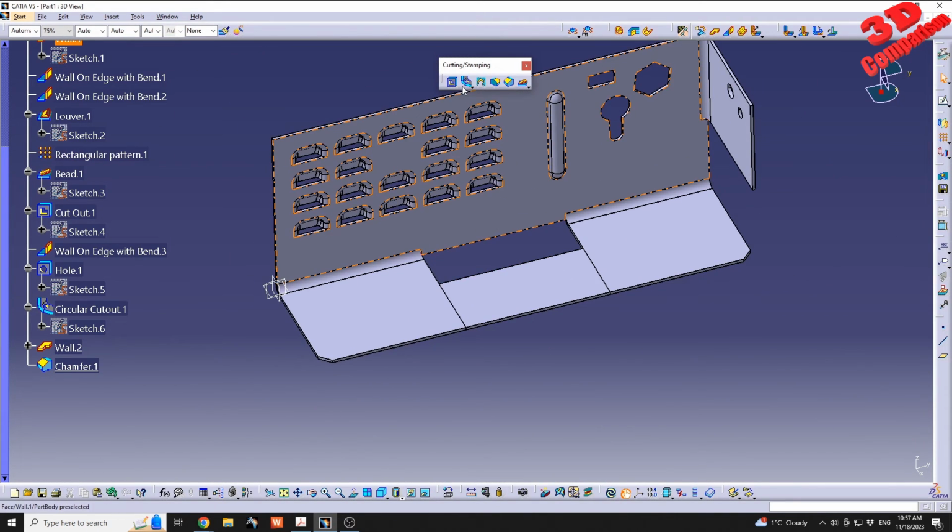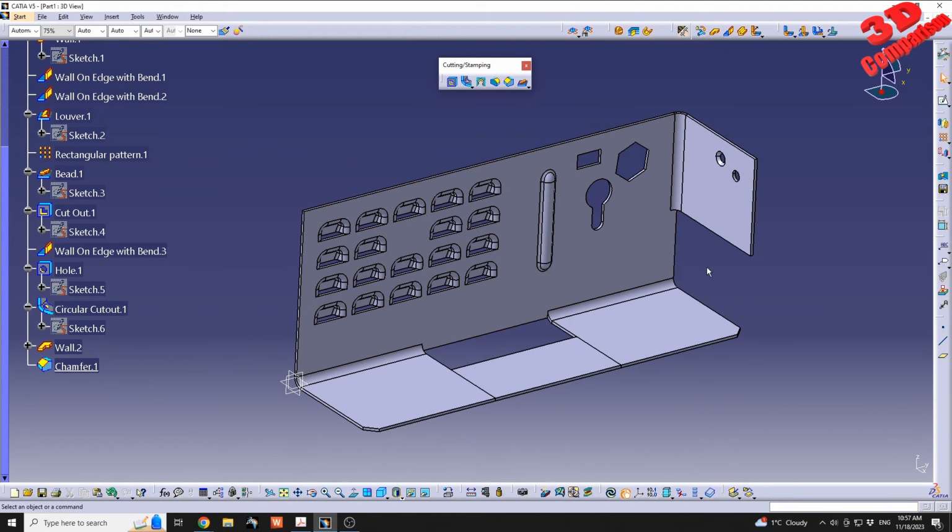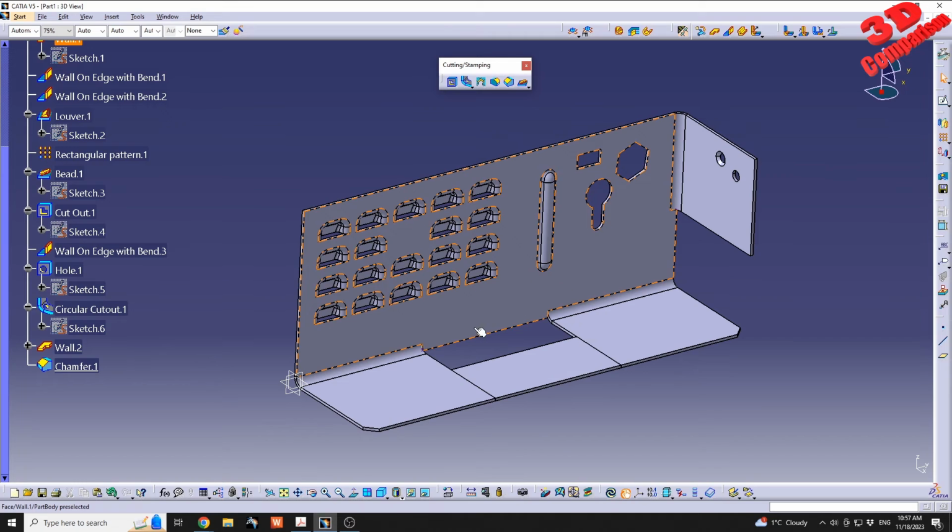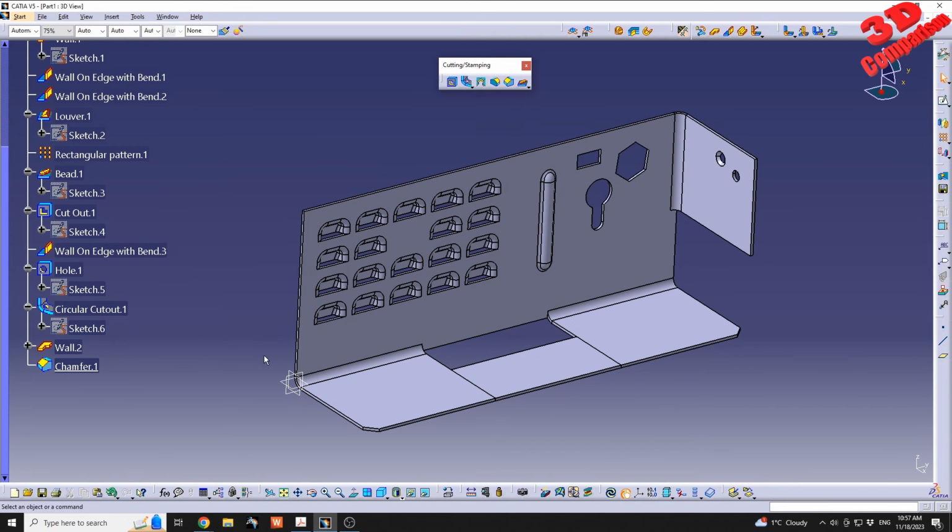That shouldn't be any problem. The whole wizard is the same, just like within part design. The only difference is that over here you will always need to define some walls, and those, if you want to have the elements connected, you need to specify tangency between those, just like we did previously over here.